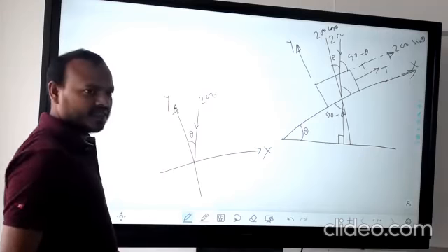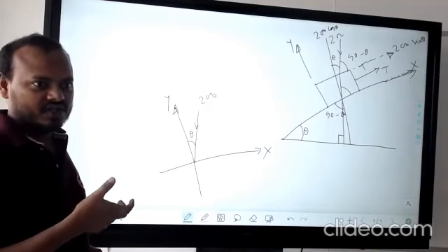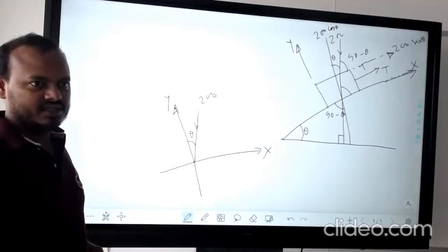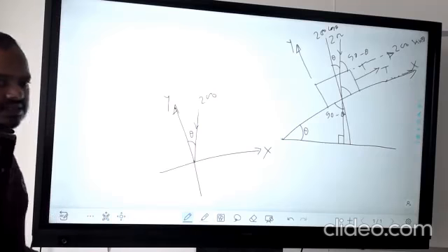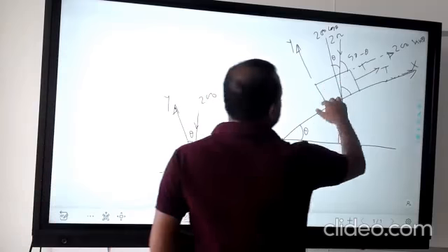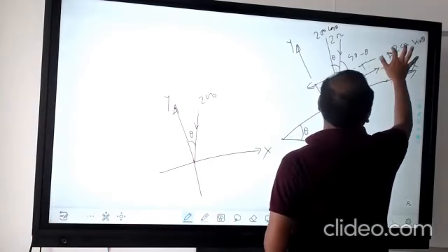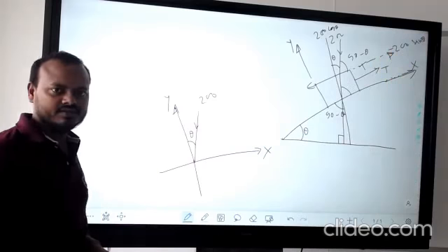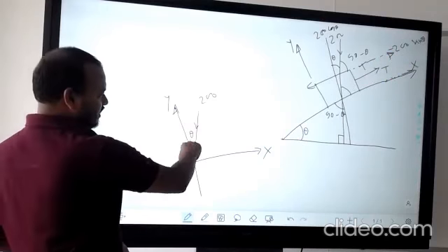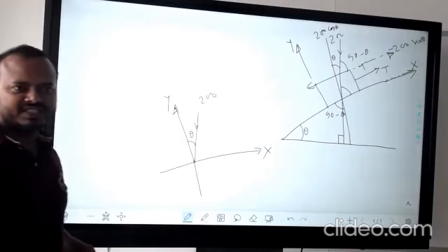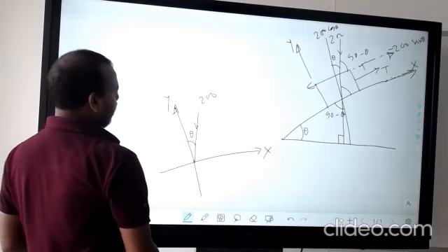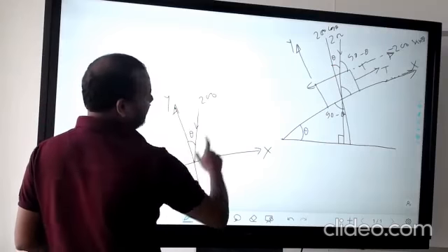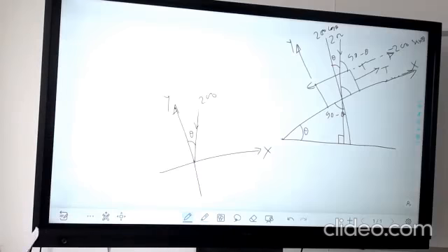Sir, up? This weight, no? The weight of the block always acts downward. Then sin theta, this side, the downward direction it will come now. And you can apply a negative sign also. I apply that sign, you can apply this. This is like negative 200 sin theta. This is the condition happening here. Not a puzzle. Last class we discussed the same things. Then solve it. So 200 cos theta, 200 sin theta, tension is given. And F is equal to mu R. Apply that condition and find out.